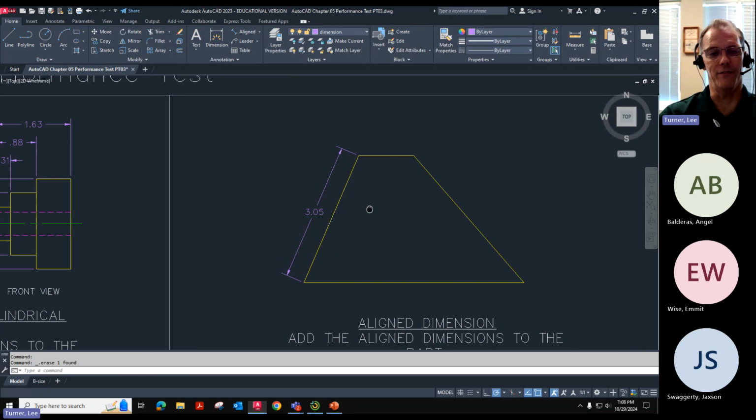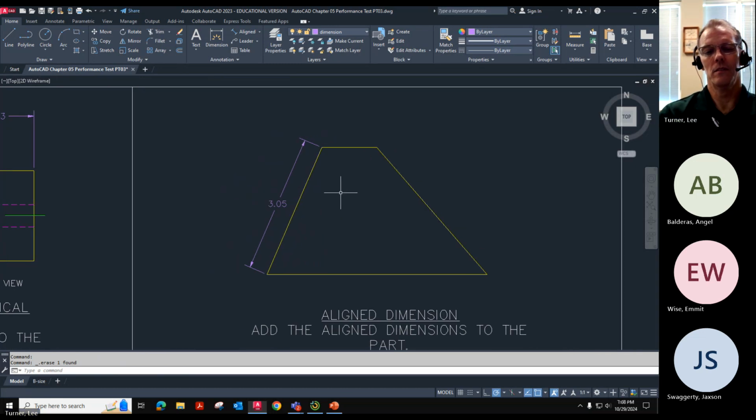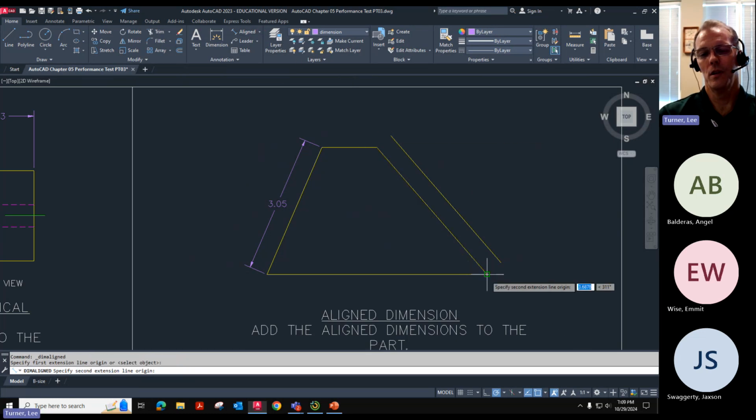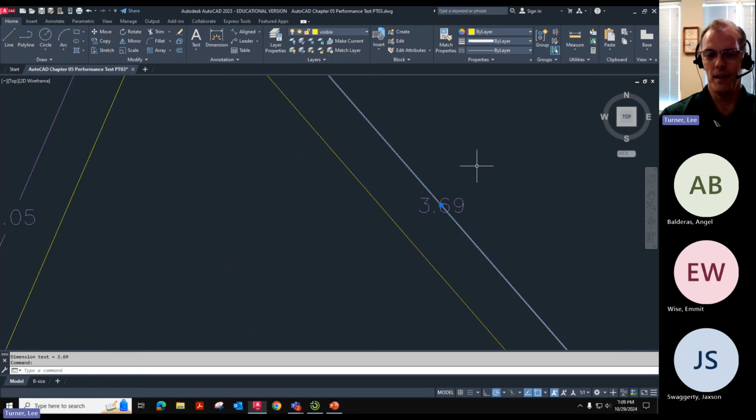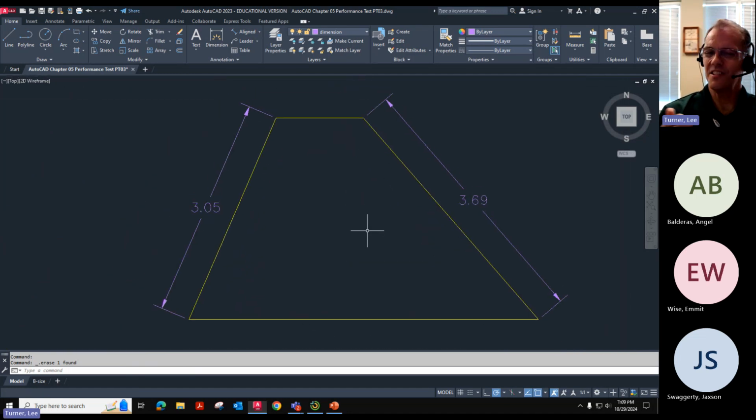If you wanted 0.5, you could offset 0.5, and then you could snap your dimension. And so what we could do ahead of time, if we anticipated or knew that, we could offset, put in 0.4, pick this line segment, and now when we click a line dimension, we can click the 2 points where we want our extension lines to be, and then we could come out and we could snap exactly 0.4 away if the tracking isn't working properly. Okay? So that's just another little tip on how to space your dimensions properly.